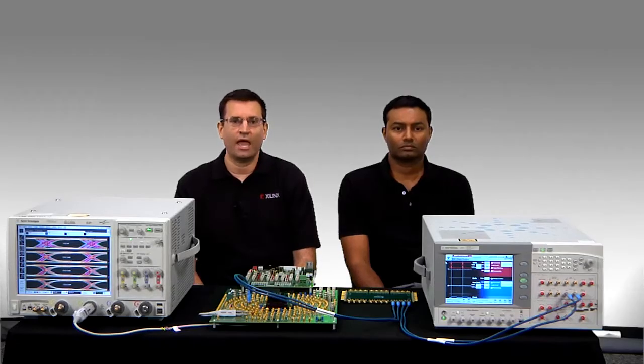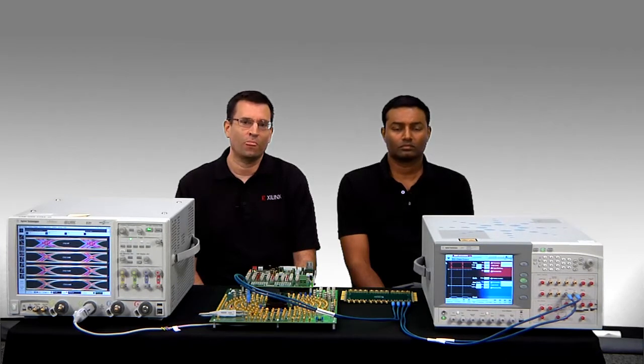Equalization, typically reserved for high-speed transceivers, is now available for all SelectIO of the UltraScale FPGAs. Every SelectIO of the UltraScale FPGA features both transmit preemphasis and receiver CTLE, or continuous time linear equalization, to compensate for signal degradation and thereby ensuring optimal link margin.